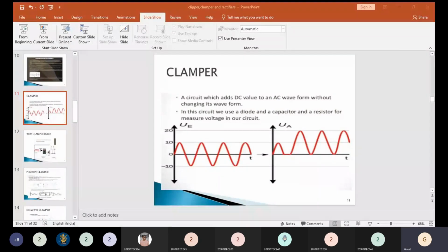Im by pi, right? So in Im by pi, what is the value of current here? In the circuit, the series combination of RF and RL is connected, and the input is Vm sin omega t. Then what is the current I? By Ohm's law, I is V by R. So I is Vm sin omega t divided by RF plus RL.